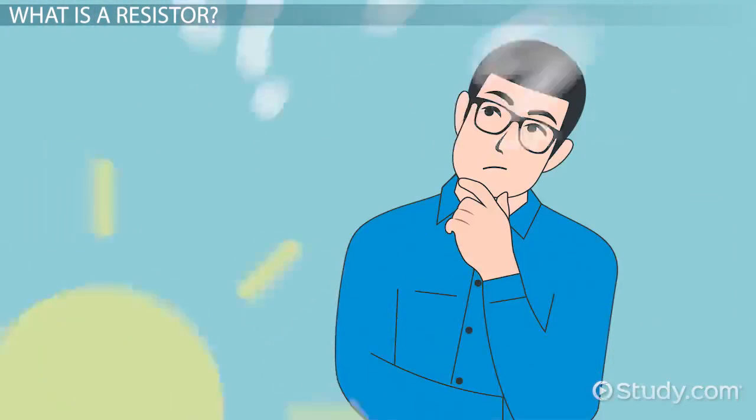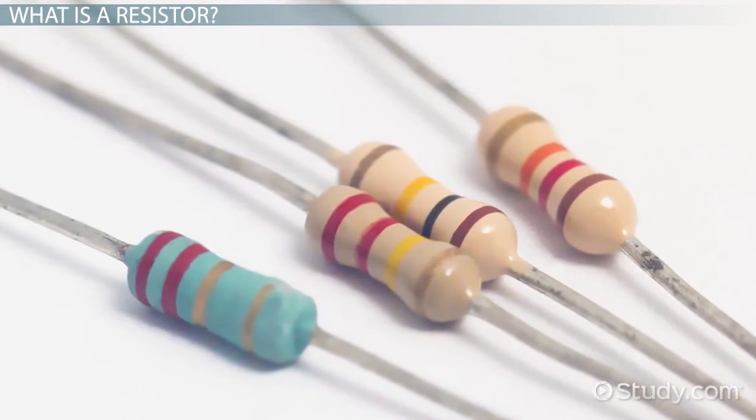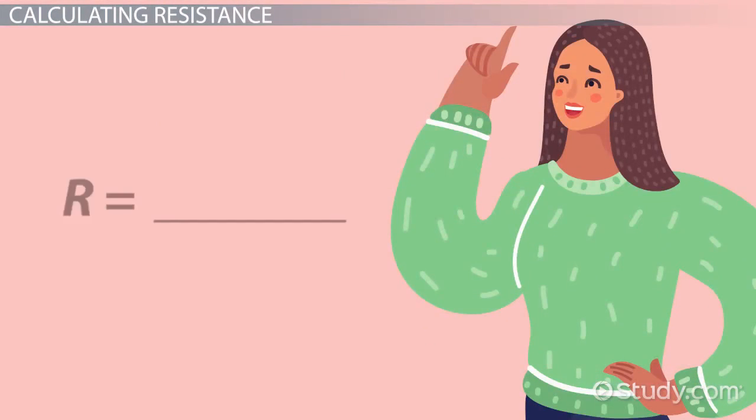There are many different resistors that an engineer can choose from. They are all rated by the amount of resistance each has. The bands on the resistor tell how much resistance it has. Because the resistance of a resistor depends on the material it's made out of, the formula to calculate the resistance takes that into consideration, which can be read mathematically as R equals rho times L over A.